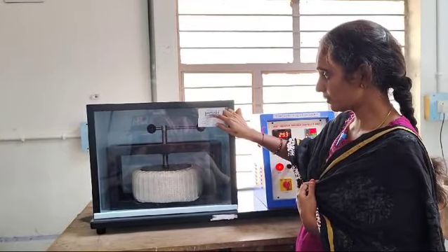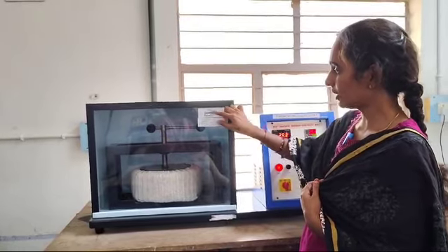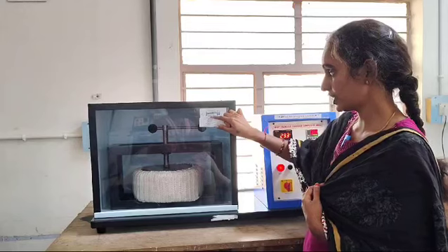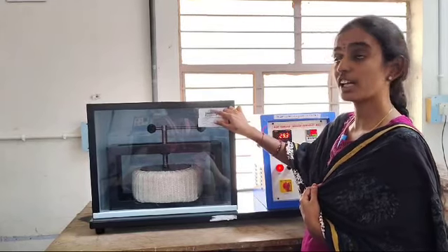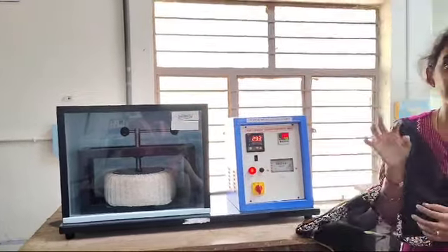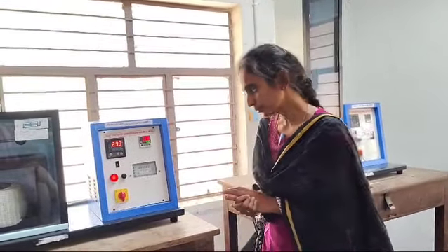The interface temperature of the heater and the cast iron on the bottom side is called T2. Likewise, the interface temperature of the cast iron and bakelite is T3 and T4. The interface of bakelite to wood is T5 and T6. At the surface, T7 and T8. These are the interface temperatures of the composite wall.